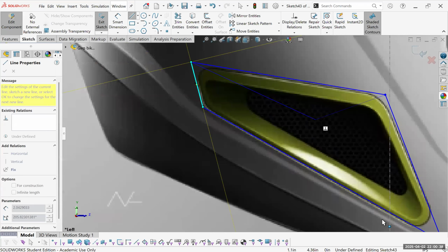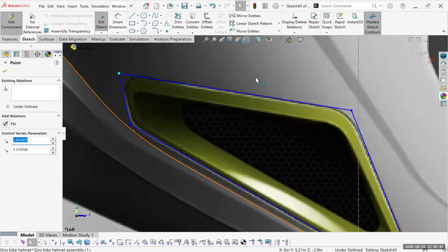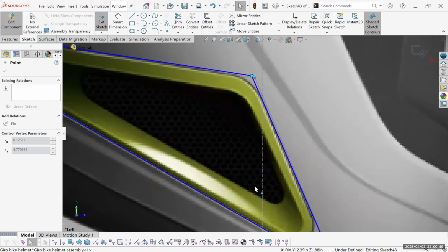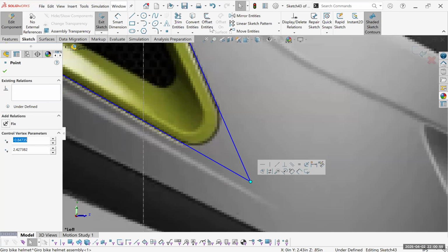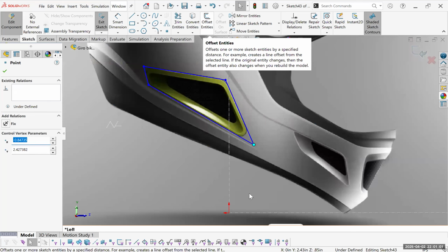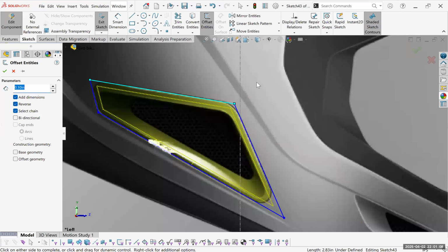And this needs to go up. Before I make a fillet, because this is double layered, I'm just gonna do an offset entity on this one, in the reverse. I will still have to come in and edit this offset because it's not equal everywhere, as you guys can see.